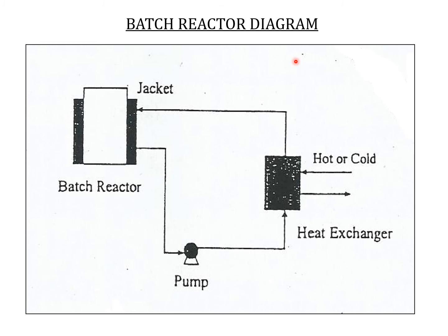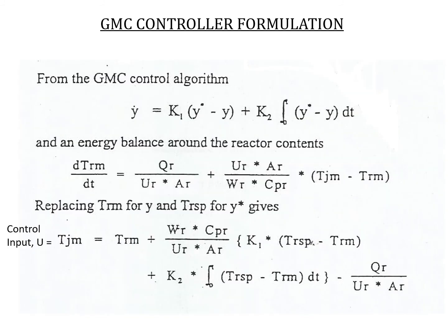Some equations don't have U linear, some have U linear in control, and so that equation can be used, just like just now. X1 we can use, X2 we cannot use. So we decide on that to decide what is our Y and what is our manipulated variable. And this has been implemented in the pilot plant.